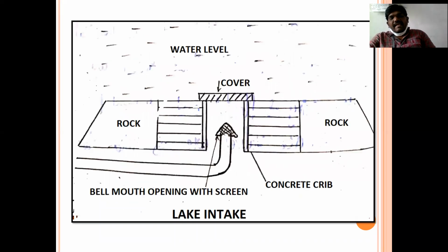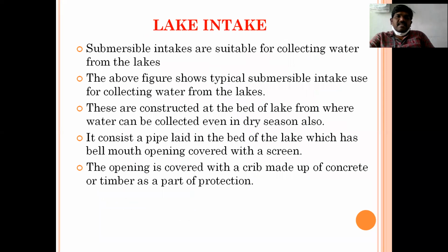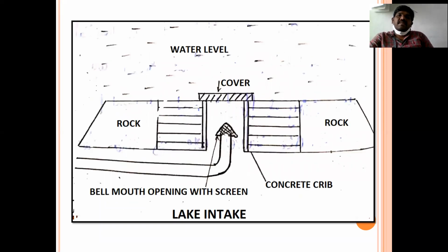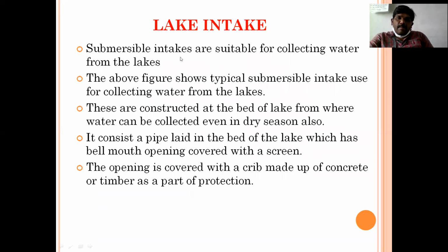Lake intake is somewhat different from the previous intakes. Here, submersible intakes are suitable for collecting water from lakes. The above figure shows a typical submersible intake used for collecting water. These are constructed at the bed of the lake, from where water can be collected even in the dry season.